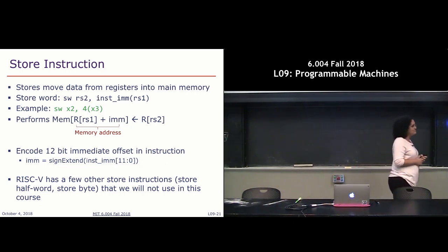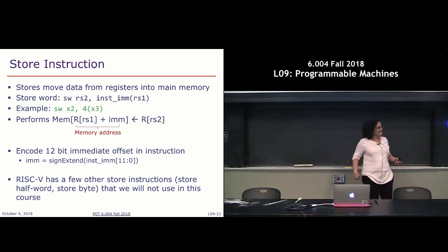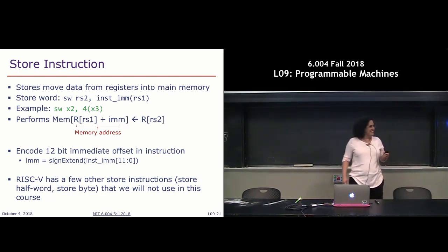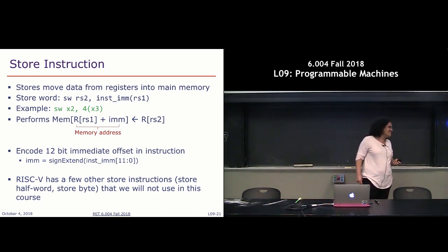Yes, you had a question? It is loading from the memory a word of 32 bits? Yes. So remember that our addresses are always pointing to 32 bits at a time. It first adds with the offset and still has a 32-bit word, and then puts that 32-bit word.